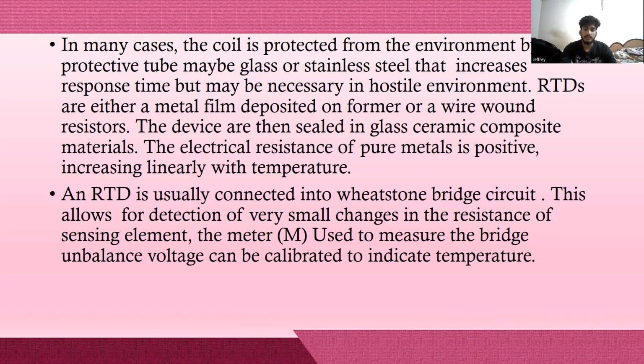An RTD is usually connected into a Wheatstone bridge circuit. This allows for detection of very small changes in the resistance of the sensing element. The meter M used to measure the bridge unbalanced voltage can be calibrated to indicate temperature.